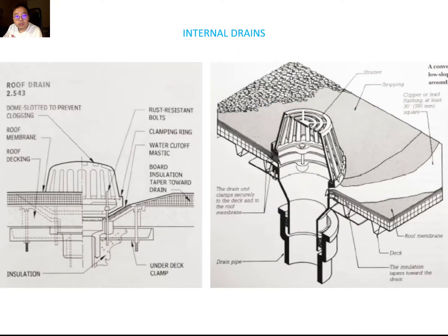So now you can see that to protect against the ponding issue, the roof needs an internal drain system. So you can see that this is an internal drain detail. You need to remember the waterproofing membrane has to wrap up the roof drainage system to protect against water penetration. You can see your drainage system, and the waterproofing membrane actually protecting this corner, the connecting condition. Okay, so this is one important part for understanding this internal drain.